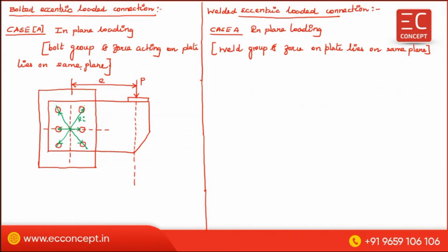Now, while resolving, this force can be converted about the centroid point as a direct load and a moment, P into E. There are two forces acting: one is a direct force, another one is a bending moment.